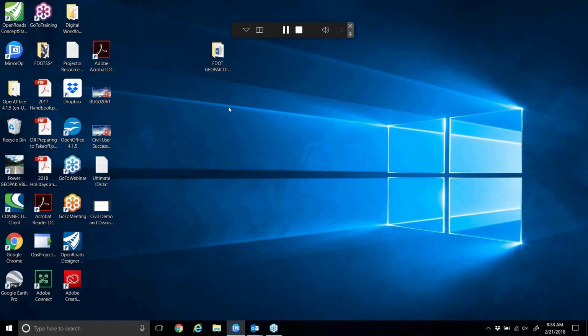So to get started, if you'll flip to page 1-2, these should all be numbered with chapter number dash page number. And I realize some of this is review from the previous class. So the files that we're going to need are called project components. And there's a whole section in our project preferences that we'll set up to go along with those project components. The main file here, and they're all listed in bold with bullet points, is this GEOPAK drainage file. It has a .gdf extension, which stands for GEOPAK drainage file. That's your database for the drainage system.